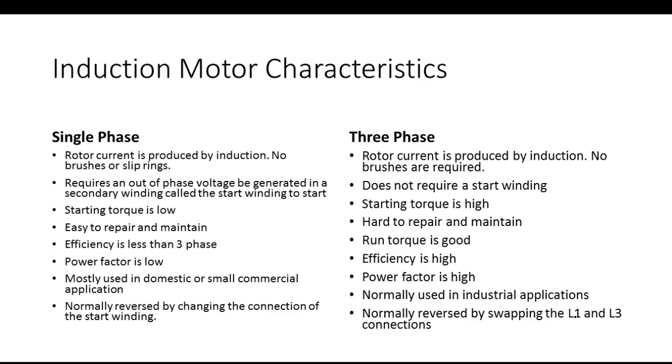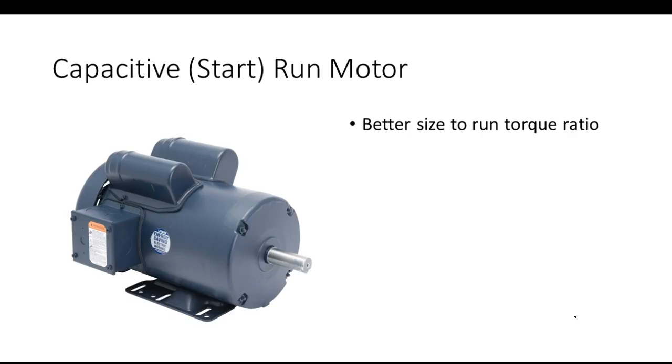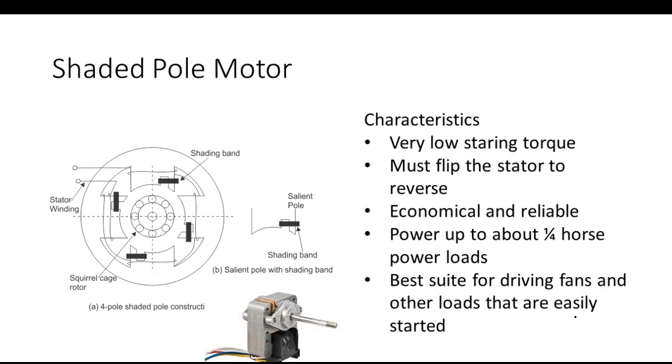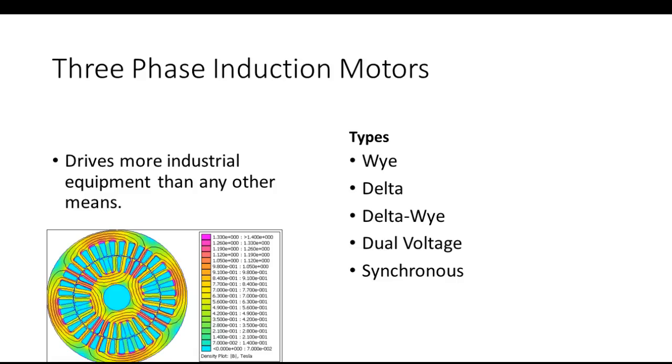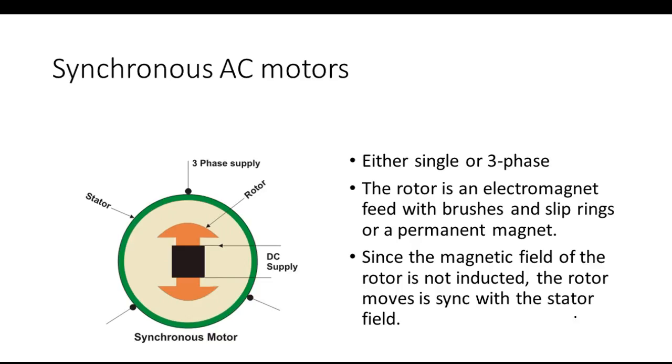How does an electric fence work? No, well, it could be. You got to be able to voltage up. Normally, what they do is it runs off of a DC pulse. And normally, the time how often it pops, it probably uses a timing circuit, a capacitor resistor. But it usually goes to a transformer. It has a transformer that sets the voltage way up.